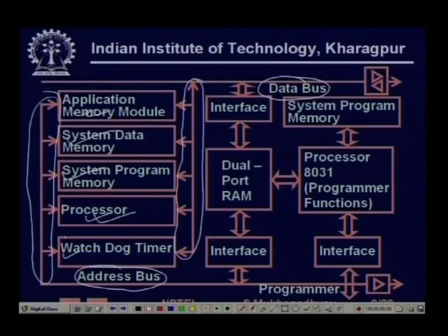Special kinds of PLC systems are, just like you must have experienced that sometimes your PC hangs, it just sits quiet doing nothing, somehow it gets mired into some infinite loop. So this is prohibited in PLC systems, if due to reasons like wrong programming or memory corruption the processor stops doing useful work. Then there have to be explicit mechanisms by which the processor execution must be brought out of it and taken into a safe state. This is typically done by watchdog timers, which are hardware devices, and if these timers find no proper activity over certain periods of time, then they by force take the processor to some safe state.